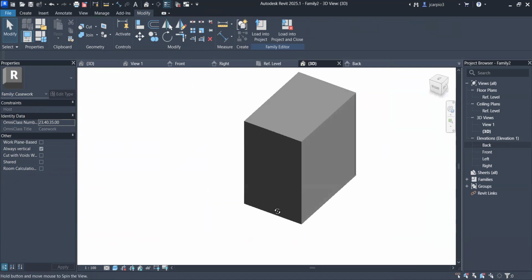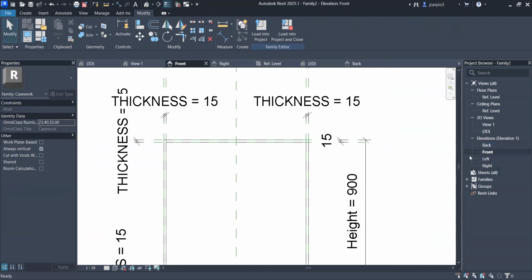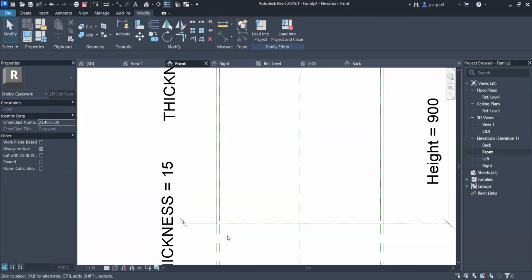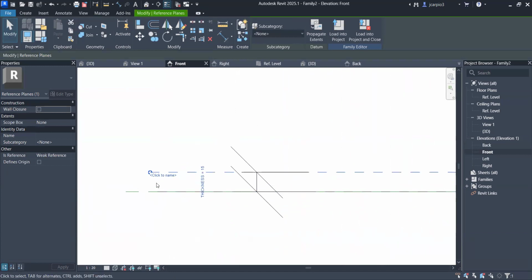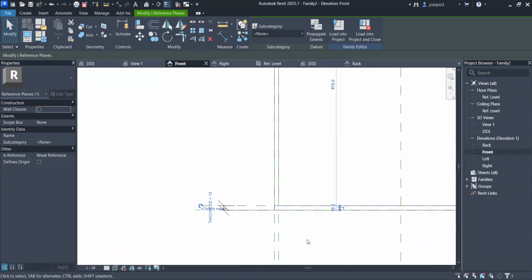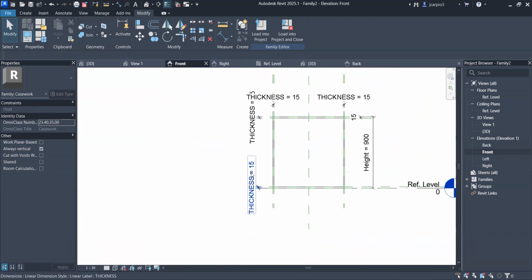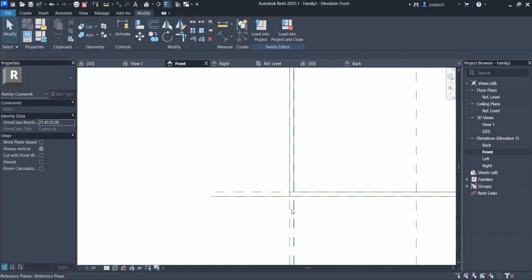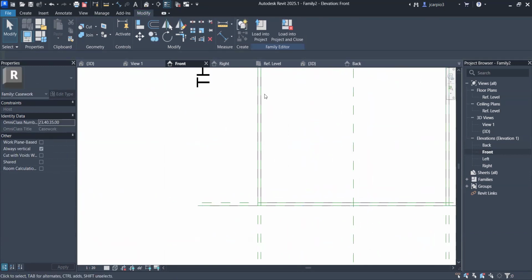And then for the front or door panel, we're gonna create it in the front elevation. And as you can see, you can click the name, modify this and have it renamed, like door panel. For this one, we're gonna just remove this thickness for a moment.